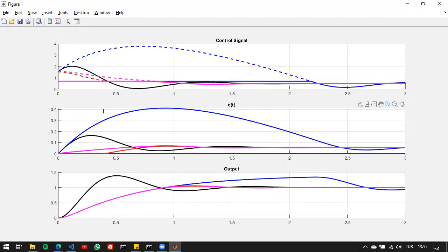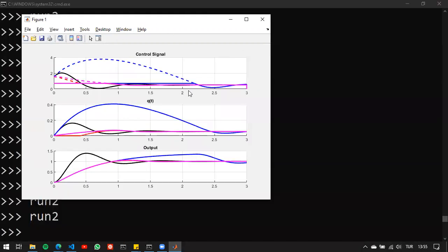Now, we should also take into consideration that if we do such a thing, we might slow down the system overall a little bit, which is a good thing if you are trying to hit the limit here, because we should avoid the saturation limit. During the limit, we have basically no control over the system at all. For systems that are not really that crucial, this might not be an issue.